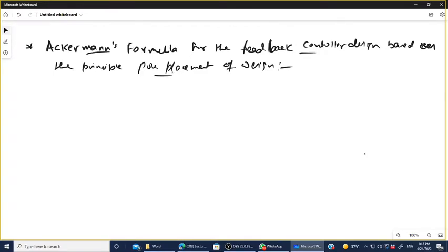In the previous lecture, we covered how the feedback controller can be designed using the method of matching coefficients. We covered one numerical, and then we also studied the design of the feedback controller using the transformation to controllable canonical form, or CCF.